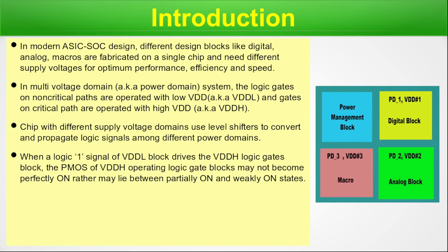When a logic 1 signal of a VDDL block drives a VDDH logic gate block, the PMOS of the VDDH operating logic gate blocks may not become perfectly on, rather may lie in partially on and weakly on states. So this might be a scenario if we do not use the logic level shifters.